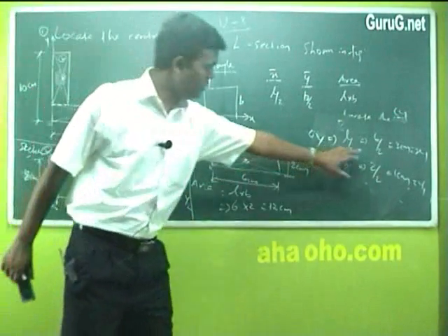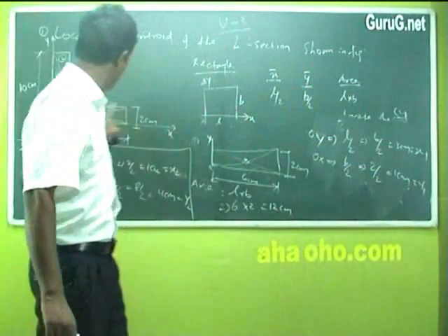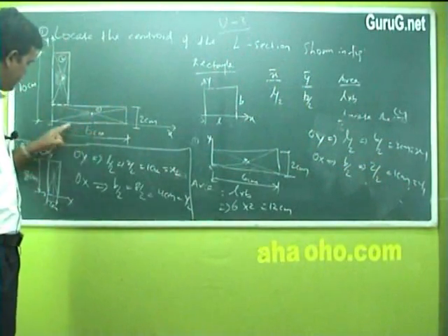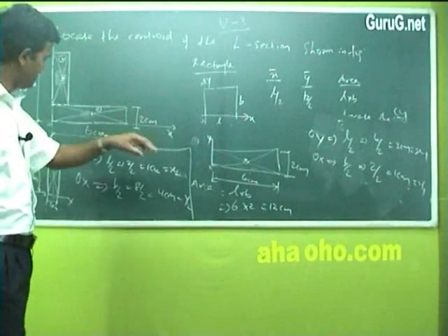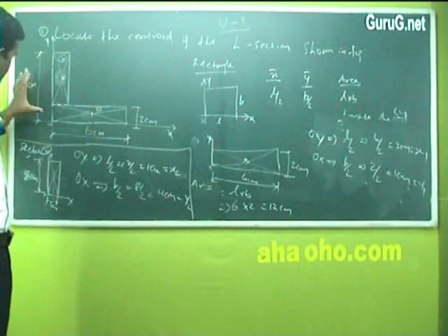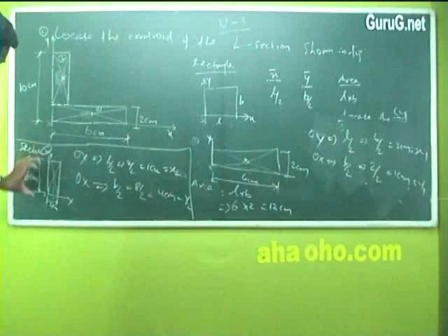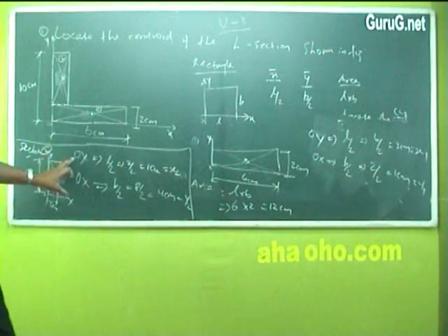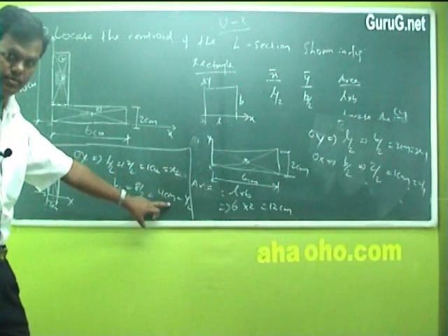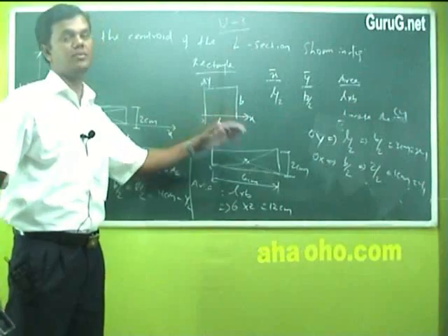Now I find out the value of x1, y1 for sketch number 1. Sketch number 1 is this small rectangle here. I have subdivided it here. And sketch number 2 is this alone. It is not 10 centimeter, it's 10 minus 2, 8 centimeter. It is written here, 8 into 2 centimeter, the sketch. For this I will find out x2 and y2.